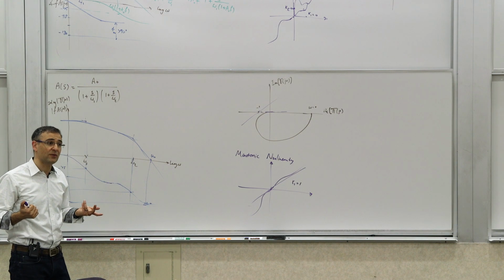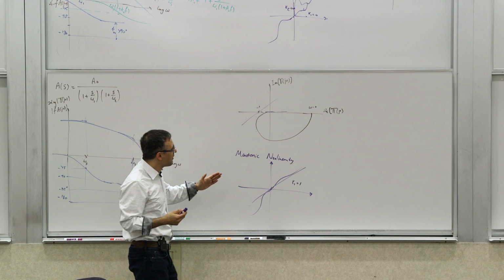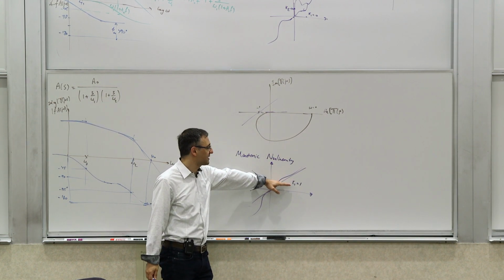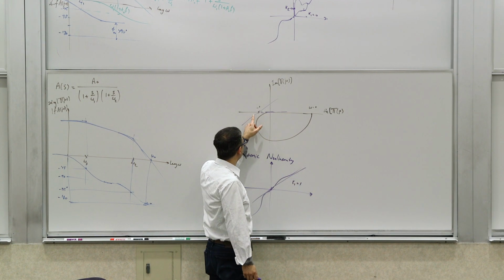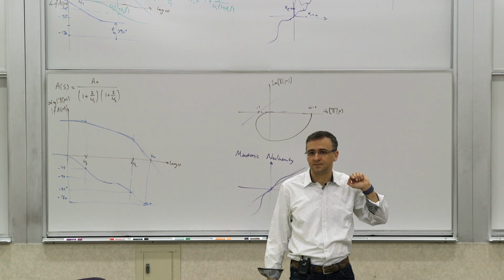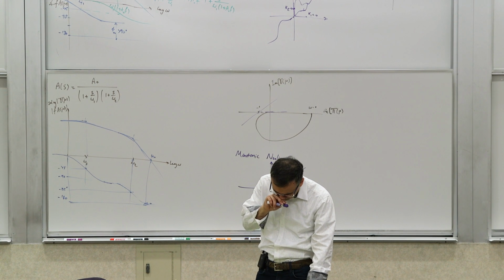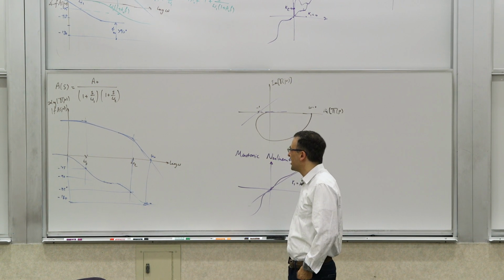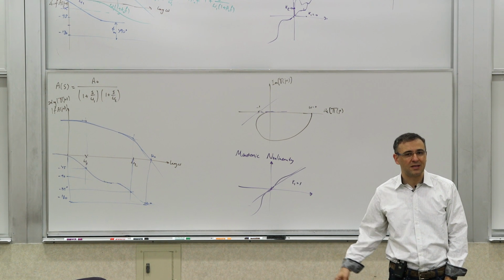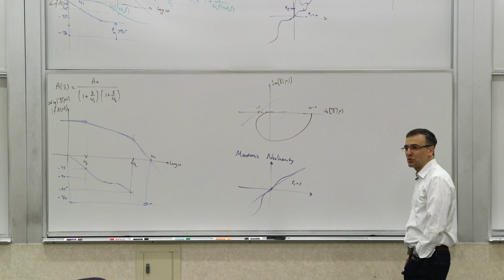So in fact, if you have a system that's nonlinear and unstable, by introducing some additional pathway so it doesn't completely saturate, you may be able to increase K1 above 0, pushing this line out, which allows you to stabilize the nonlinear system that way. So these are potentially useful things to use. And that's why generally it is hard to make oscillators with this kind of second order system, with a system with two real poles.